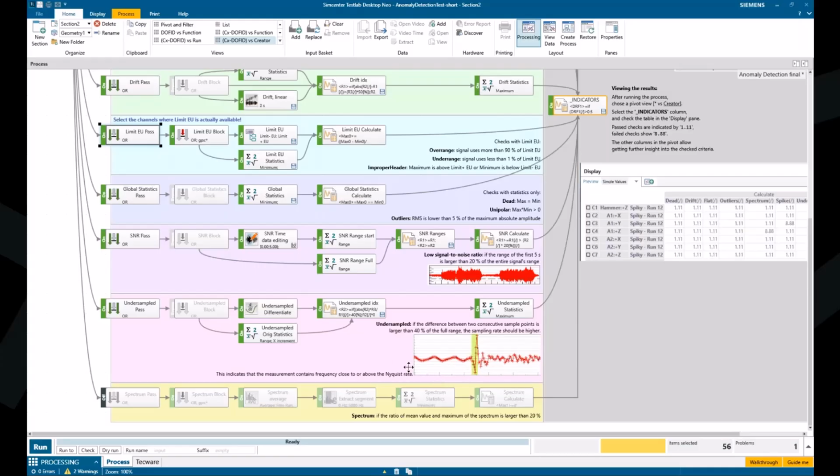In this example here, you see in the beginning, that's a nice sine wave, and it's sampled pretty well. We have enough sample points picking that up. But then suddenly here, there's a steep change, and whether the frequency in this part is captured correctly, yes, might be the case, but it also could be much, much higher, and the sampling rate prevents you from capturing that correctly.